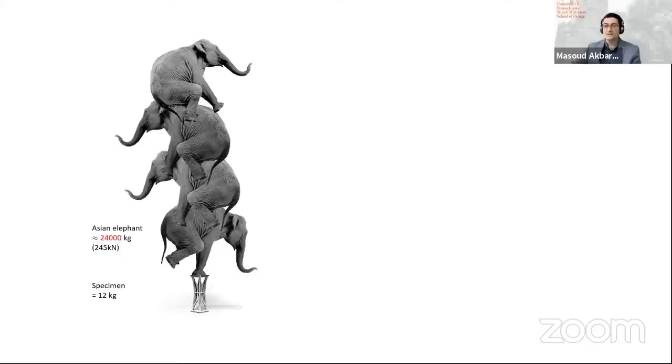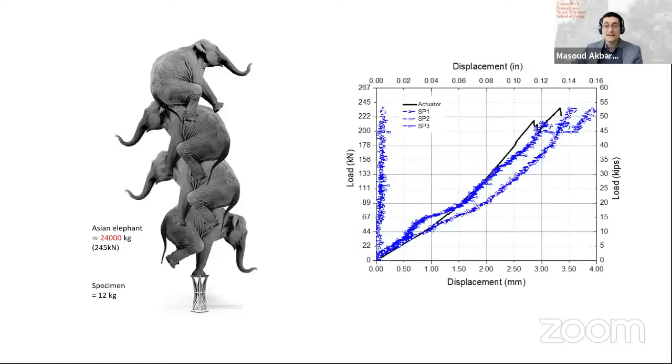So what are the lessons that we learned here? That the funicular system can have internal geometric indeterminacies, which makes the system resilient compared to a single-layered funicular system. That means that if one of the members buckles, the system would still transfer the load to withstand the external loads. The notion of constant stress in the system can be very well explained by the explosion of all parts at the moment of failure. And of course, the load-bearing with respect to the weight ratio is quite high, which shows the efficiency and lightweightness of such structures.